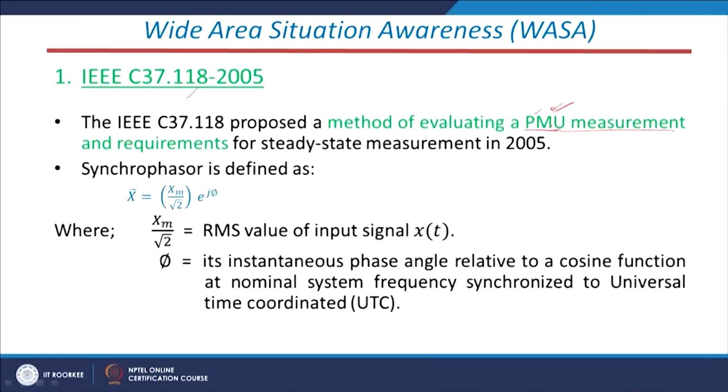What is that PMU? What is the function of the PMU? For this PMU measurement also we have some standards. Basically this PMU provides all the information: voltage, current, frequency. So, the standards are meant for this PMU measurement. In some terms this PMU is also known as synchrophasor, because the PMU operation is in synchronization with the universal time clock.